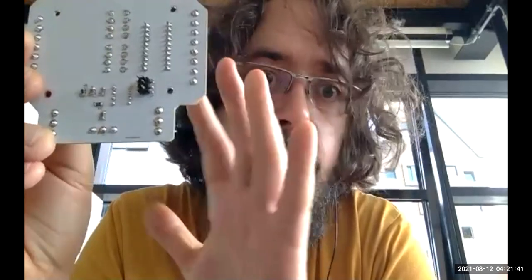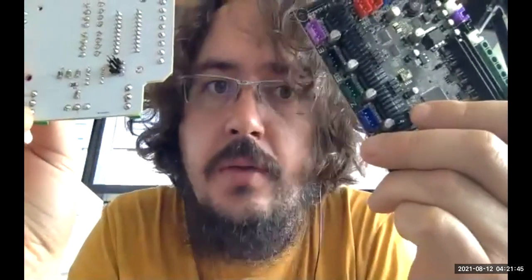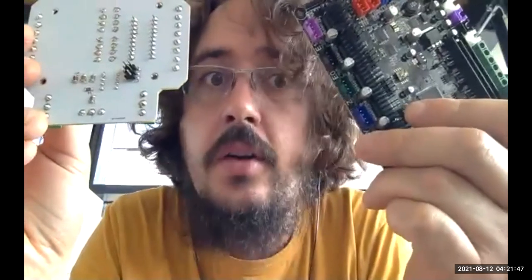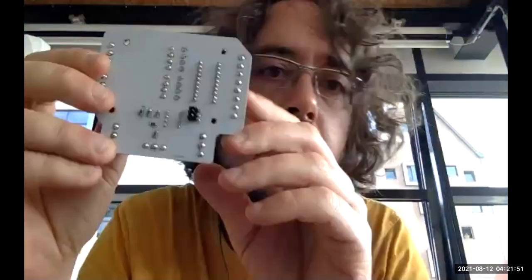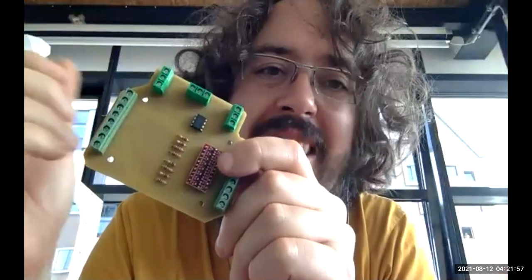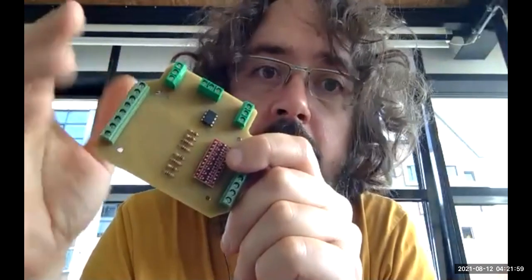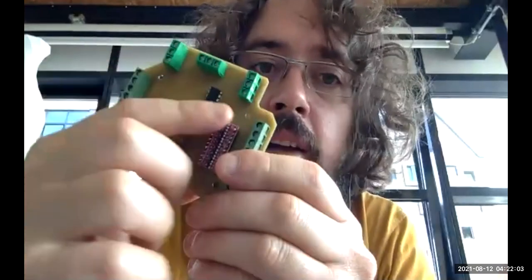It takes pulse width modulation, PWM, but it works at 5 volts, while our board outputs only 3.3 volts. So we need to make a logic converter. But not only that, we need to make sure that this logic converter sends the signals at a specific frequency, because if the logic converter is rather slow in outputting the signal, then you're not going to engrave anything and you get horrible results. So that's why we added it.